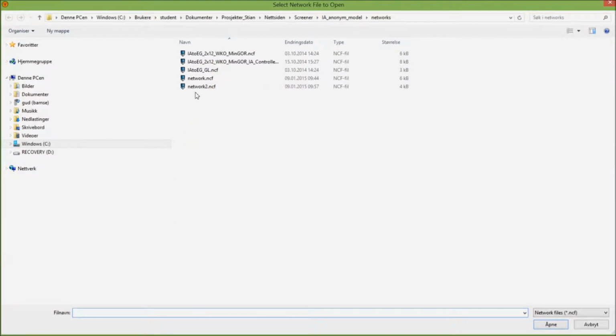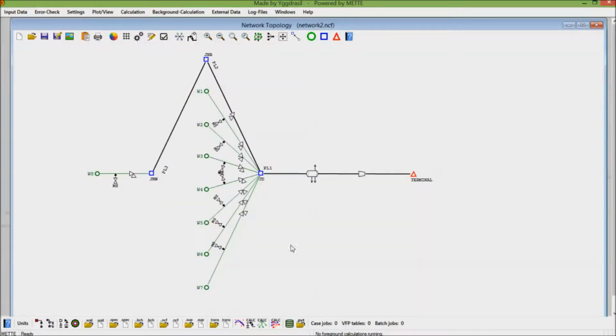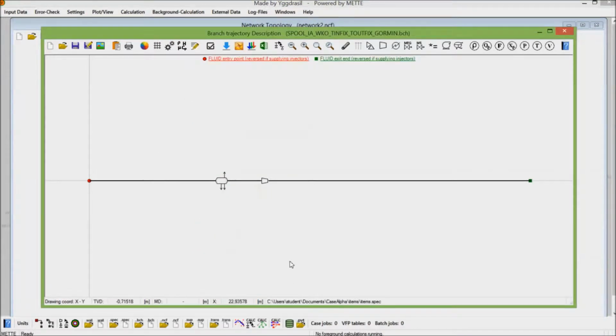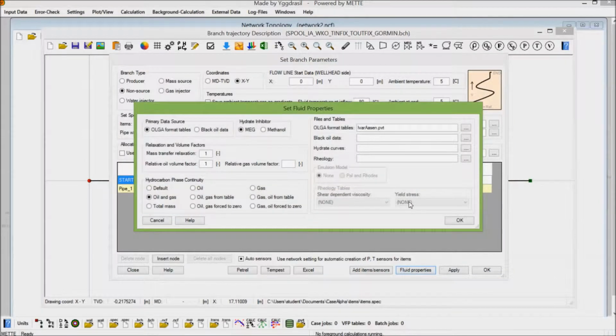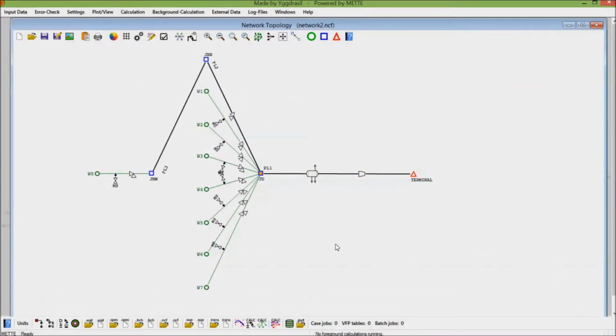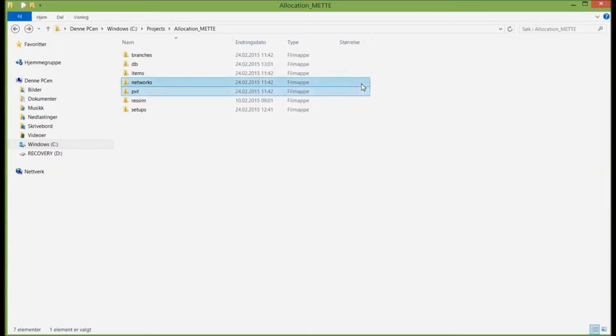To enable life-of-field simulations, specific input data must be provided. This includes parameterizations for items or components used in unit operations, flow trajectories for wells and flow lines, fluid properties, and network incidences. Finally, the input must include references to run files for any reservoir models, as well as events which are used for well openings and setting of system targets and constraints.